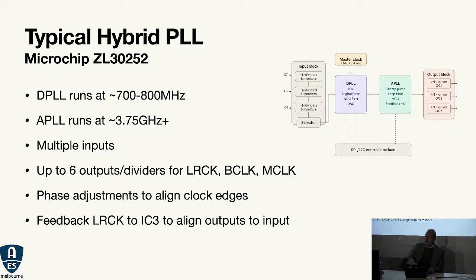And it will synchronize so that the input and outputs are always time aligned. Jitter on this, running things to get an output at 24.576, a typical number would be about 1 picosecond, in the 1 to 2 picosecond range.